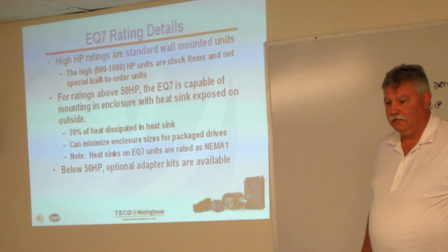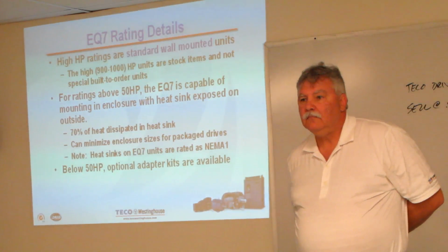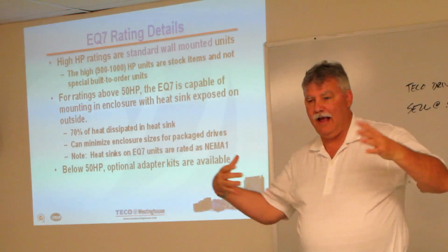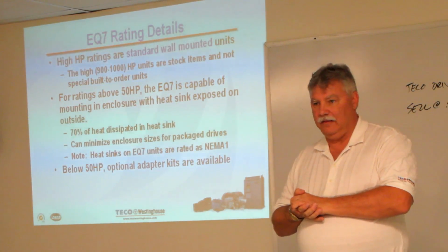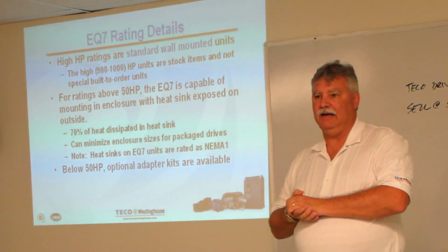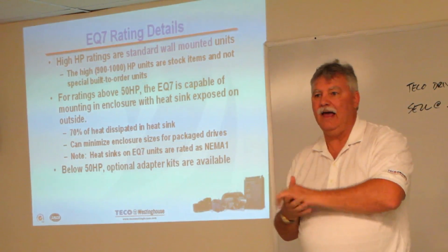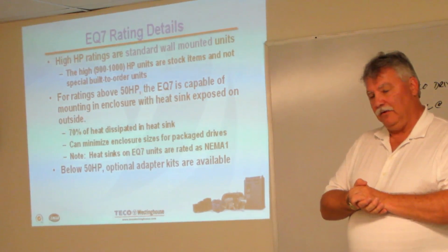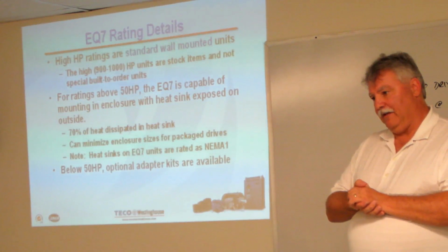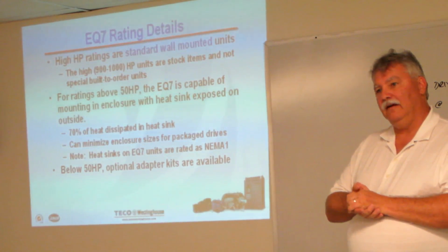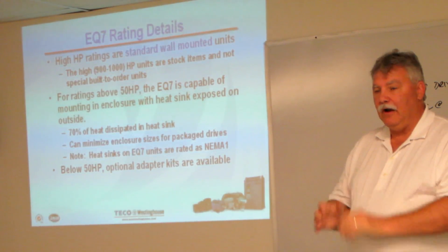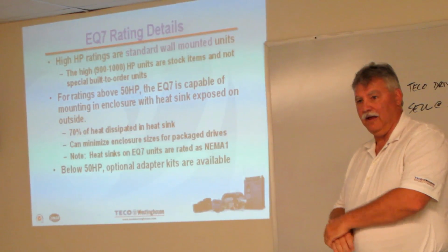Is it weatherproof, the heat sink weatherproof? The heat sink is a NEMA 1 rating, so it would be more like the front of the cabinet and the front part of it would be the thing there. But the heat sink doesn't really have a lot of live electronics. It just has the metal, and it'll have a fan going through there. So it may not be as critical if water gets back in there. I mean, yeah, if it's dirty and dusty, these things do plug. They may plug up if they're not periodically inspected and maintained. So I do have to give you that caution.